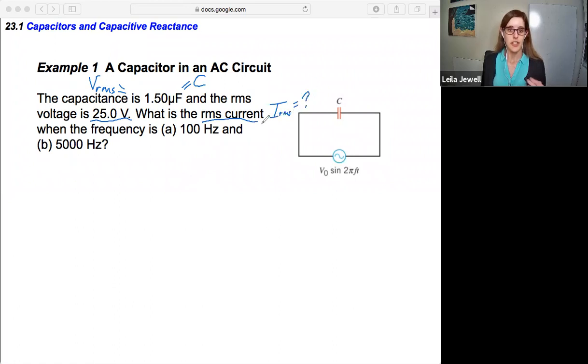And if you were listening and saying, hey, capacitance, that's similar to resistance, then you might be led astray into going, hey, we can just do Ohm's law, right? V equals I times C, right? There's a problem here. What's the problem? Ohm's law doesn't work with the capacitance. It works with the reactance, the capacitive reactance to be specific. So even though I was just trying to X out the equation, it actually worked for the X, which is what we'll actually use here. We can only write Ohm's law, V is equal to I times the capacitive reactance.